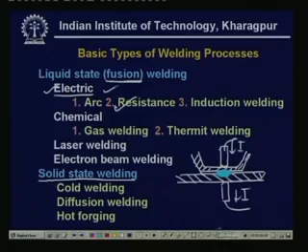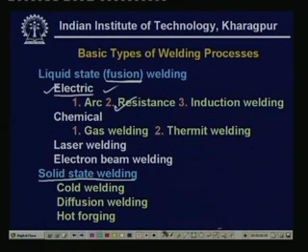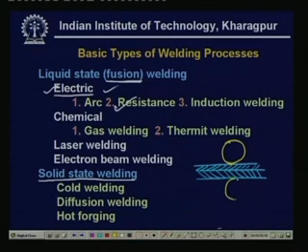Now, we have seam welding, which is just a running version of spot welding, where we have the electrodes in the form of two rollers. Suppose this is one metal and another metal. We pass them between two rollers made of copper, and a large current passes. Then we move the whole thing together with a velocity v, and when it moves, we see a line of welding, and this is known as seam welding.